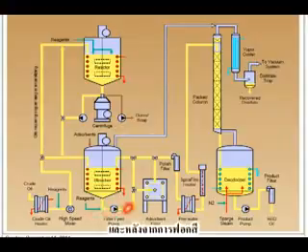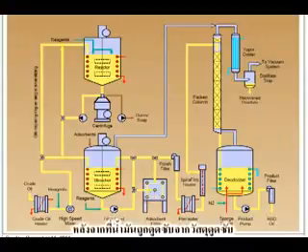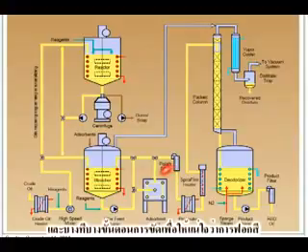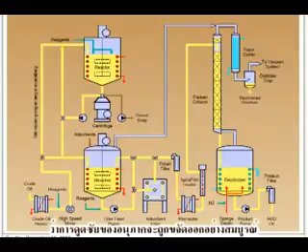And after the bleaching, the oil will be pumped through a series of filters to separate the oil from the adsorbent material, and perhaps some polishing step to ensure the spent bleaching earth particles will be removed completely.